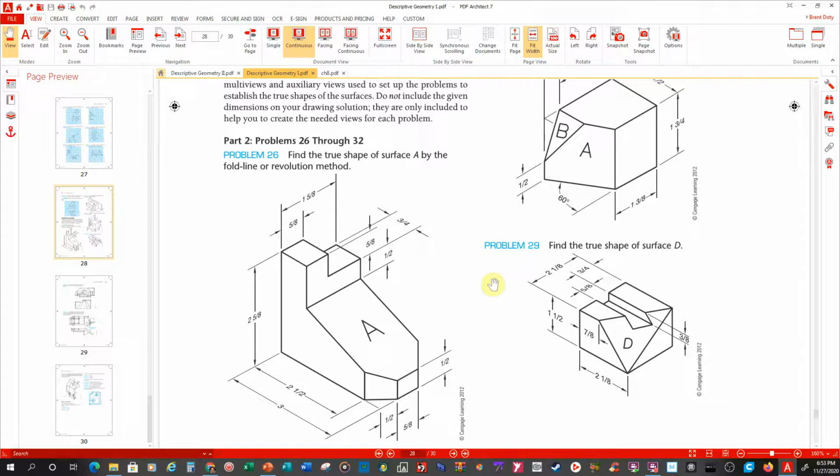and we're just touching on the surface of it, okay? For those of you that have taken some parametric modeling, either Inventor or SolidWorks, we can rotate our models around to look at the surface that we want to look at. Well, when we create views of those surfaces, of those parts, we have to create things called auxiliary views, or if it's not parallel to any kind of surface here, this one I would probably have to do 2 auxiliary views.